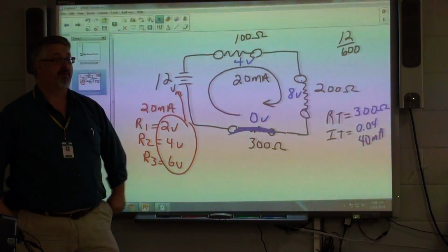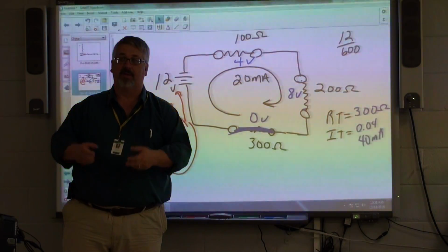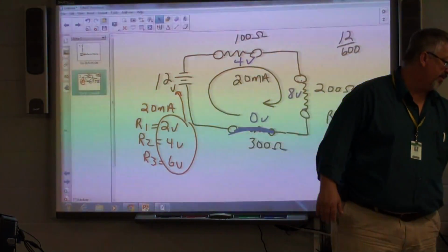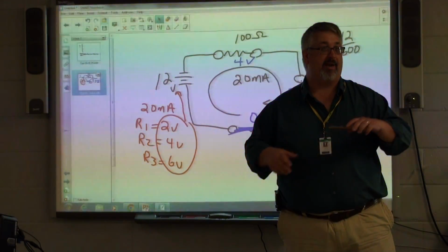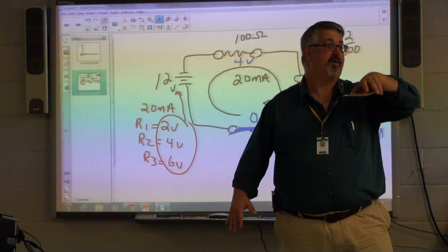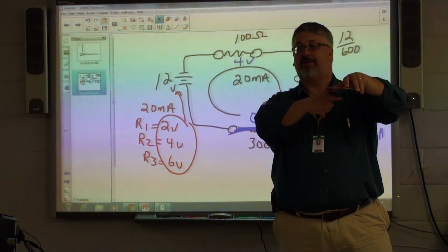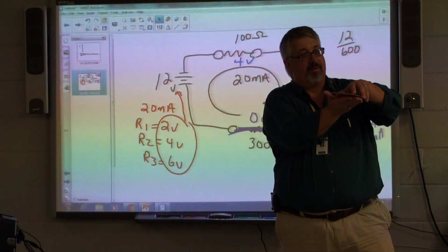And it can happen through those leads not being trimmed. We used to have solder splatters. The way these circuit boards are built at Rockville and most every other plant, there's not a person out there with a soldering iron hand soldering all those joints. There's a machine that has a rolling wave of hot solder that the board glides over.